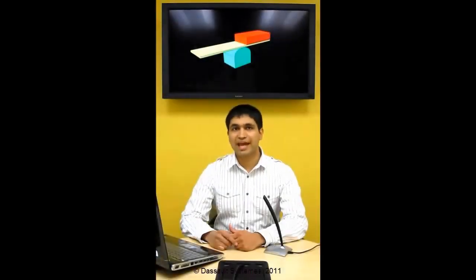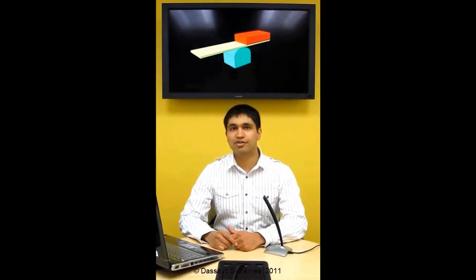The analysis will be carried out in three steps: the initial step, a make contact step, and an apply force step. Contact is a severely discontinuous nonlinearity. By having a separate step to establish contact, we make work a little easier for the solver and prevent chatter, thereby reducing the number of iterations required to solve the analysis. We will talk more about this in the course of the tutorial. So let's get started.